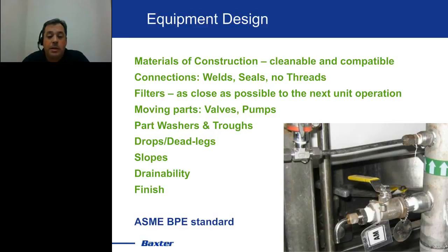So we already talked a little bit about dead legs. Those are certainly important drops. Really, you want to get rid of all of those that you can. If you have to have drops, which sometimes you do because you have components that are going to be connected and disconnected, they need to see the same treatment regime as the rest of your system. You need to make sure also that your systems are sloped and drainable and have proper surface finishes.